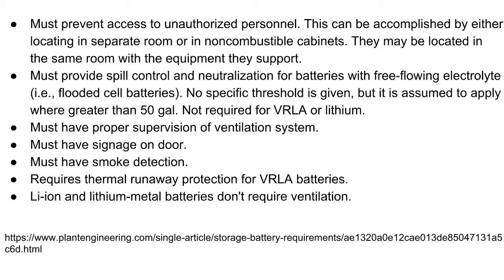Thermal runaway protection, what's that? Well, basically, it's that your batteries need to have a temperature sensor on them. That's not a very expensive piece. Your batteries are going to have a temperature monitor on them, even on the cheaper off-grid inverters. It's very common. It's like a $12 item. They sell it as an add-on, but it's not really an add-on.